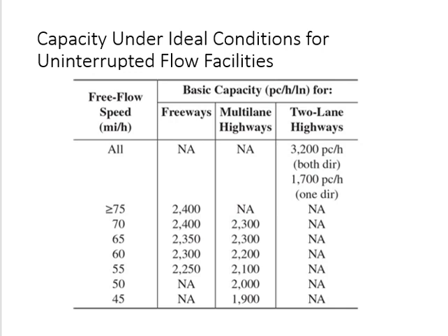So why doesn't it go to 1700? Because of the other lane. Not because this lane is different. Both lanes are the same. If this one has a shoulder, this one also has a shoulder. This one has 12 feet, this one also has 12 feet. So even if both of them are the same, when this reaches a higher value, it will start affecting the other lane. And the other lane will automatically stop at a lower value. Alright? So this is the impact.